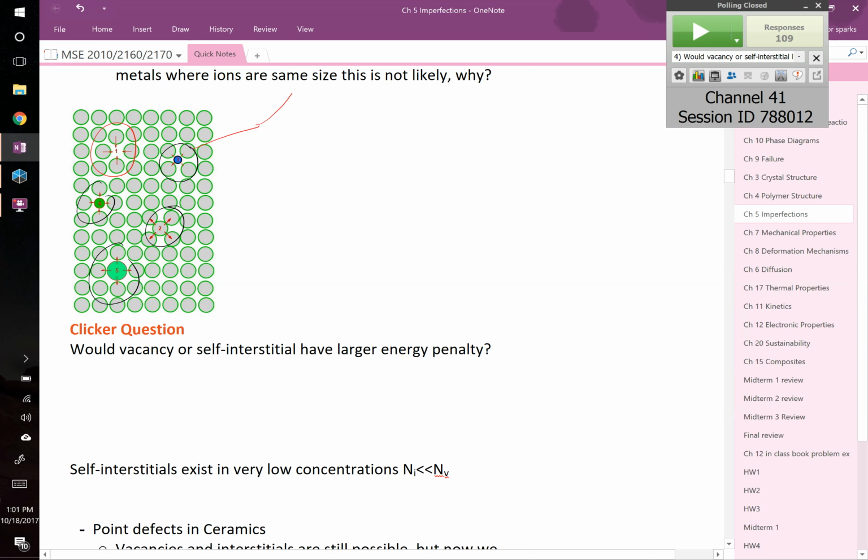A self-interstitial would be an atom the same size as the gray ones, right? So that's not actually drawn in this figure here. Number 2, I drew actually right next to it. Yes, that is a self-interstitial. Need my eyes checked, right? So 2 would be the self-interstitial.